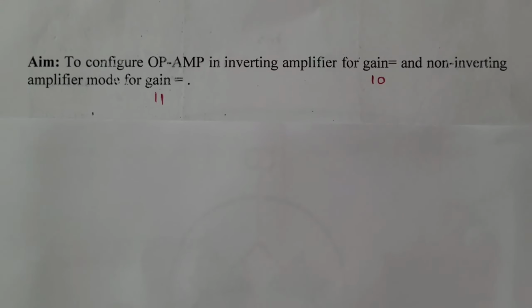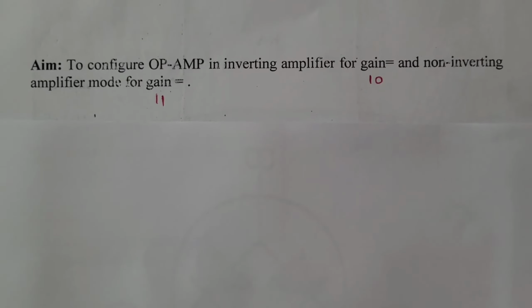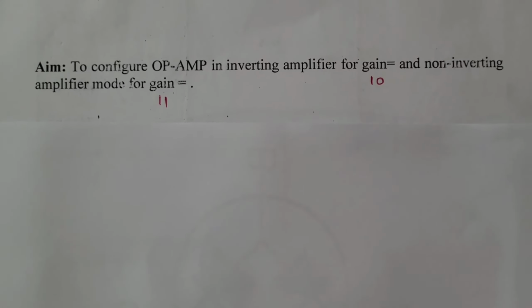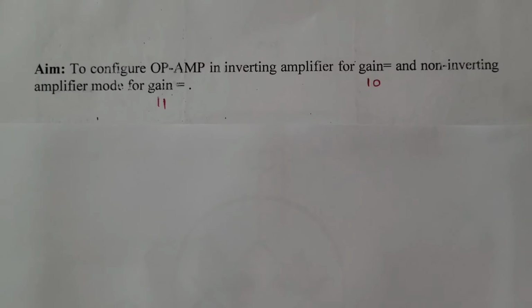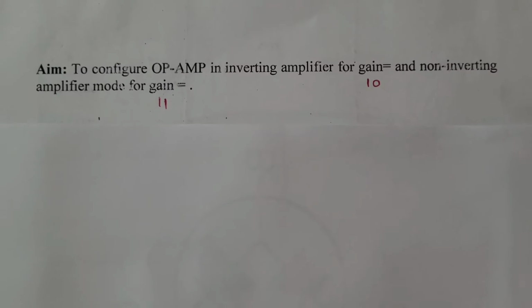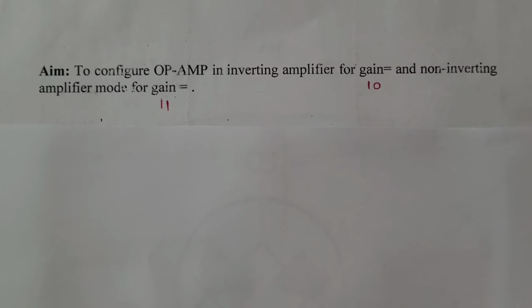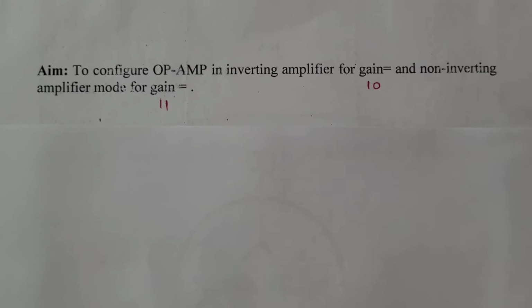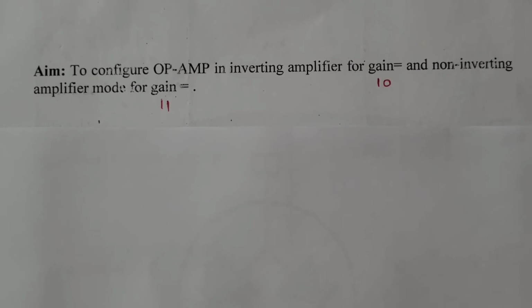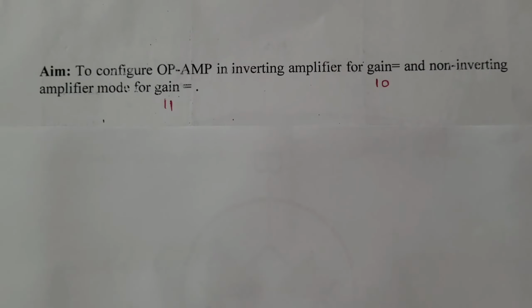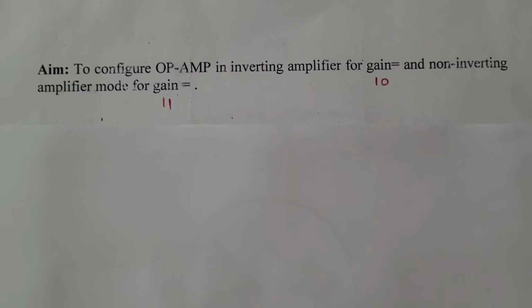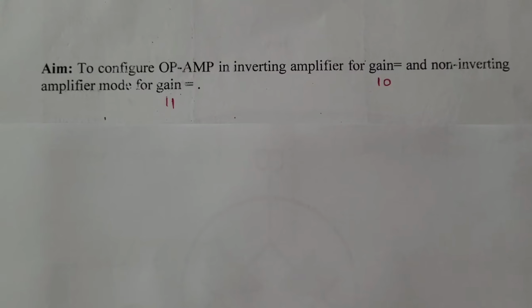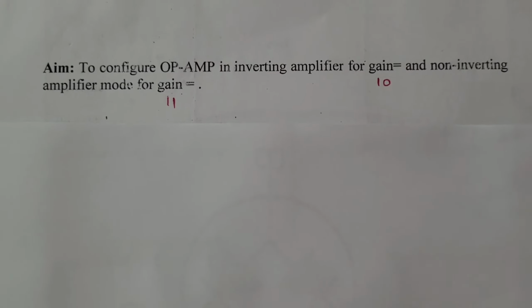Hello students, we are going to design and configure Opamp in inverting amplifier mode for gain 10 and non-inverting amplifier mode for gain 11. The apparatus required are function generator, DSO, DC source, LM741 IC and resistors.